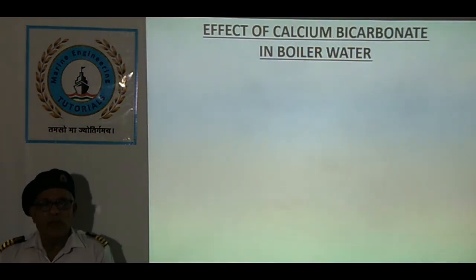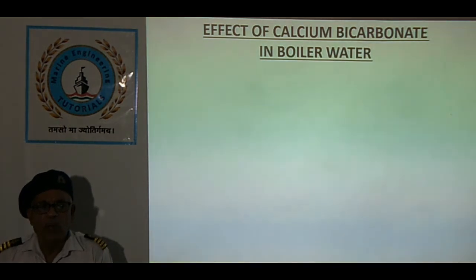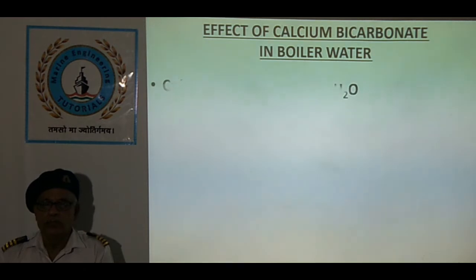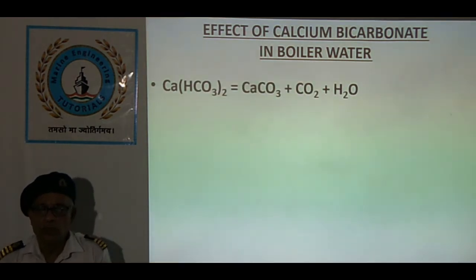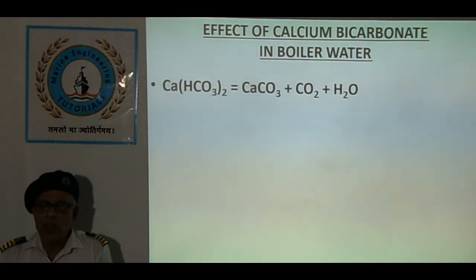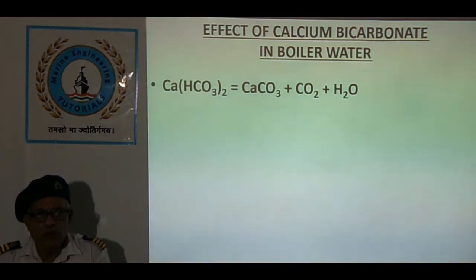Let us see the effect of calcium bicarbonate in boiler water. Calcium bicarbonate is decomposed when heated, liberating carbon dioxide and permitting precipitation of calcium carbonate.